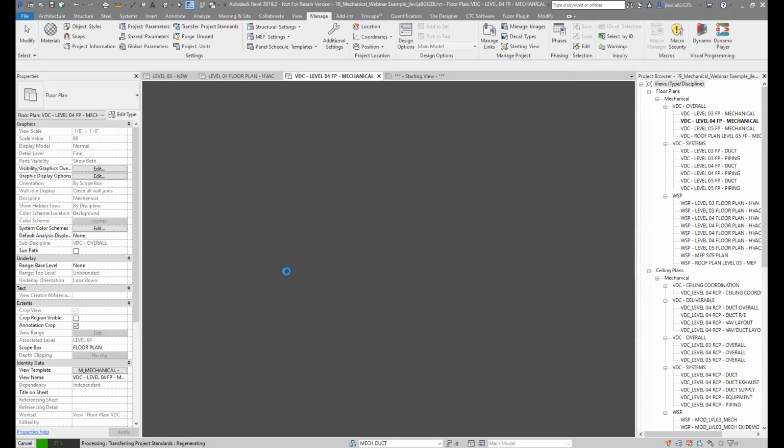Also, something with those VAV boxes that started the project out really well when we were kicking off was having that clearance zone embedded into the family already. So I didn't have to worry about going into said engineering firm's VAV family, cleaning it up, and then adding its own clearance zone. That's already done with what I currently have. So that's something I bring across, some of those pieces of mechanical equipment.